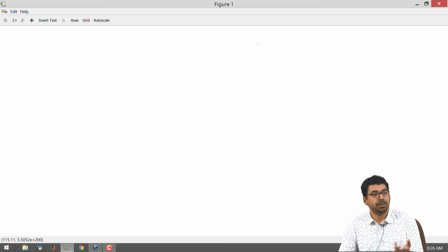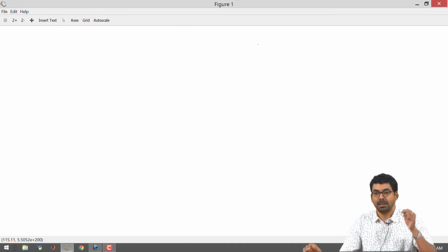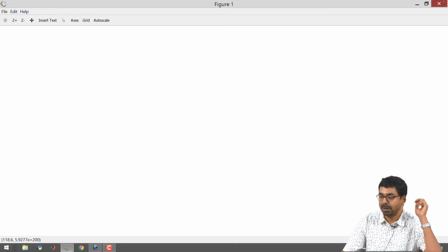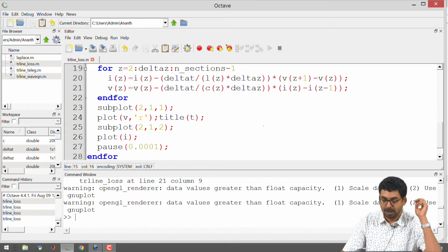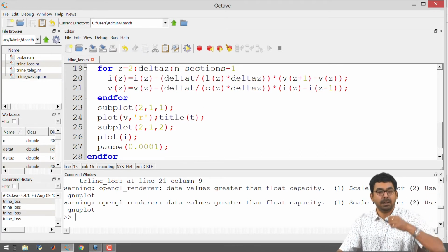In such cases, you should quickly go back and see whether your choice of delta t, delta z is appropriate, in such a way that in one instant of time you are going to the next space step or not. You can always choose the value of delta t divided by delta z. I have not included a velocity term yet over here, u, right.